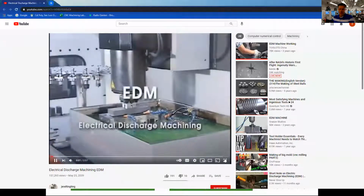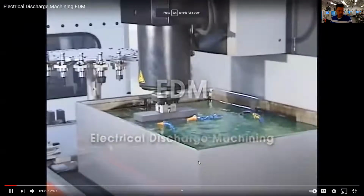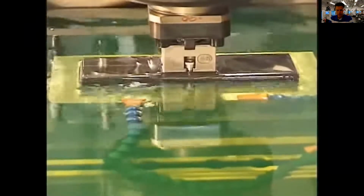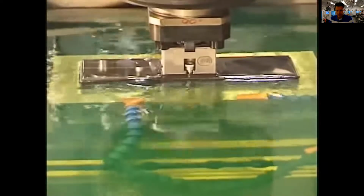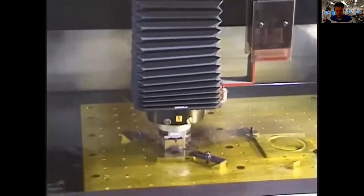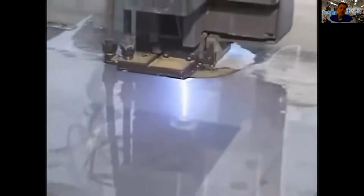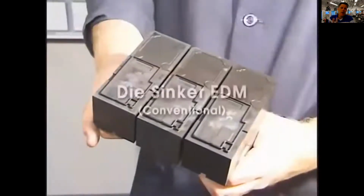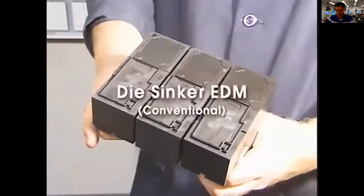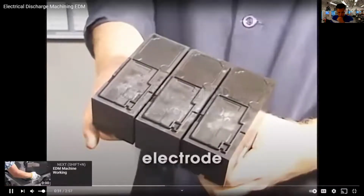Electrical discharge machining, referred to as EDM, is a stress-free form of machining since there is no direct contact between the machining element and the workpiece. There are 3 types of EDM commonly used in today's mold-making industry: conventional die sinker EDM, CNC die sinker EDM, and CNC wire EDM. It's either conventional die sinker EDM machines use electrodes which contain the detail that is to be machined into the metal workpiece.